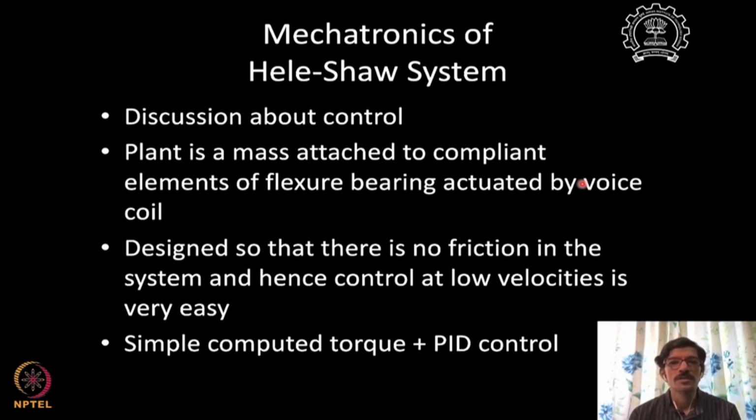Okay, it will change from fluid to fluid, and from experiment to experiment there might also be some small changes that will be happening. So that's where the feedback concept comes into the picture, very handy. See, we have designed this system such that there is no friction in the system. So then control at low velocities will be relatively easy.